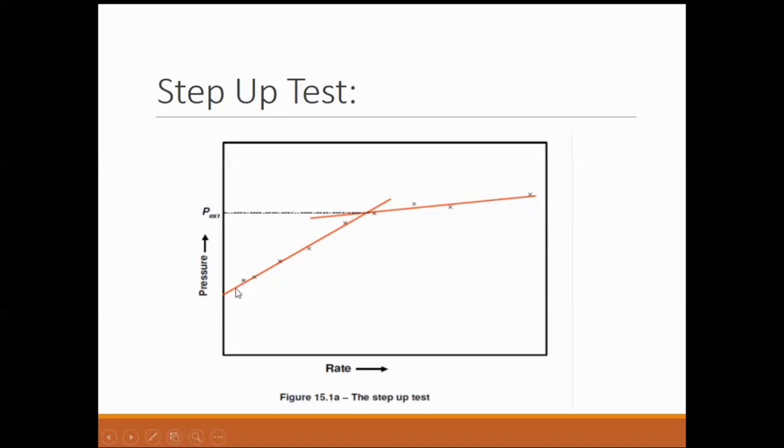If the surface tension between the frac fluid and the rock matrix is minimized, the frac fluid will tend to adhere more to the rock matrix. So it would be very difficult to recover such fluid, which has a tendency to stick to the formation. So the flowback additives basically invert the wettability, or the rock wetting properties, of that fluid. And these flowback additives are designed keeping in mind the kind of formation that you're fracking and the kind of frac fluid you're using for fracking.